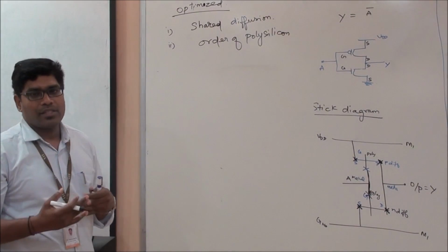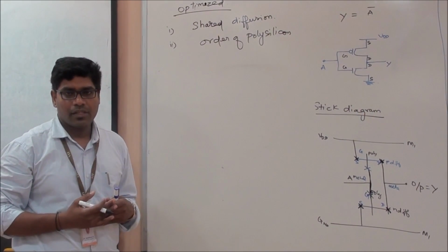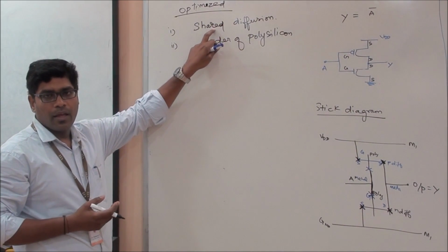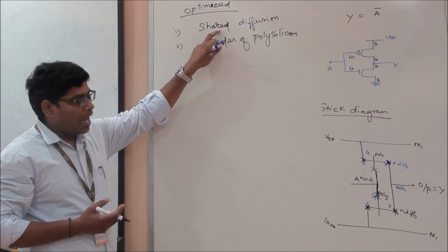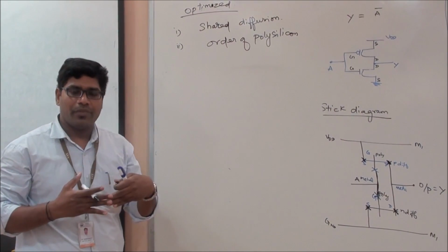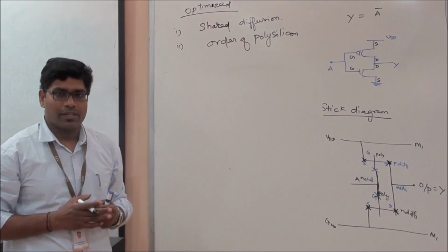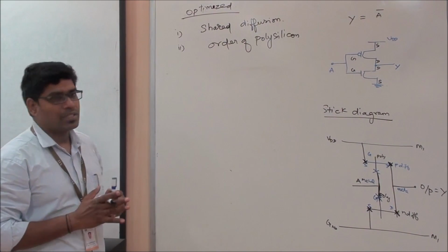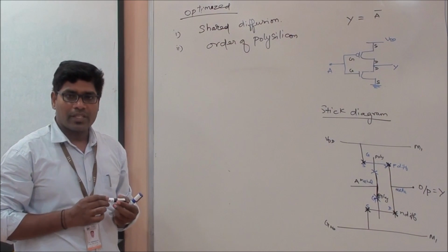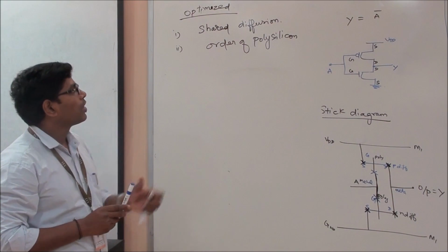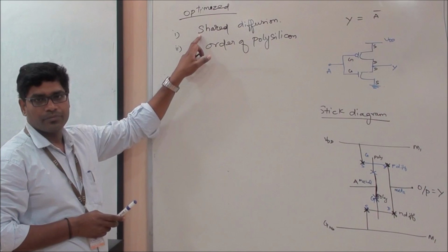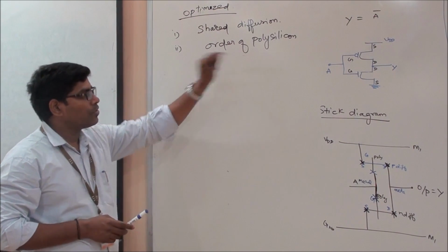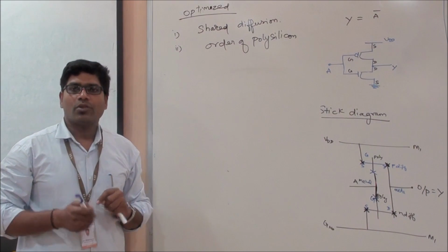The order makes a difference. In order to ensure a shared diffusion, I will not have a standalone diffusion for each and every MOS transistor.